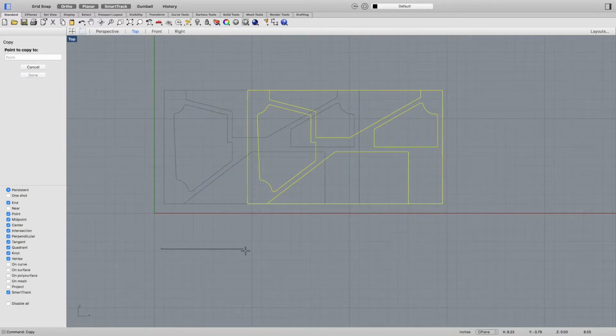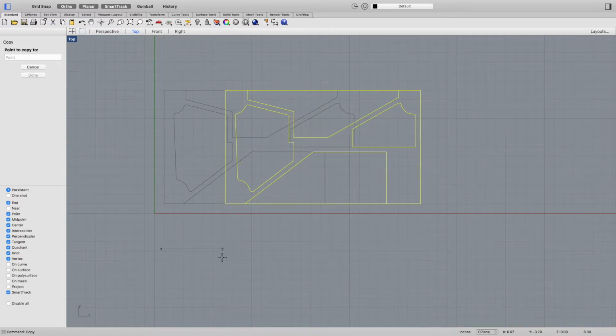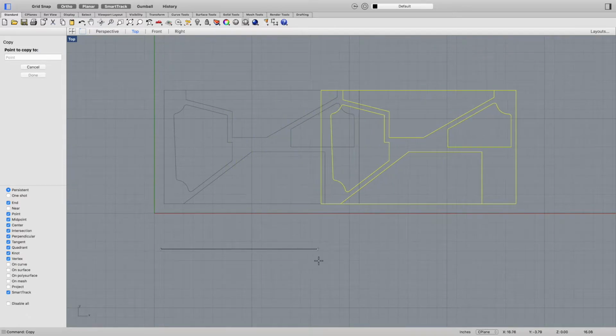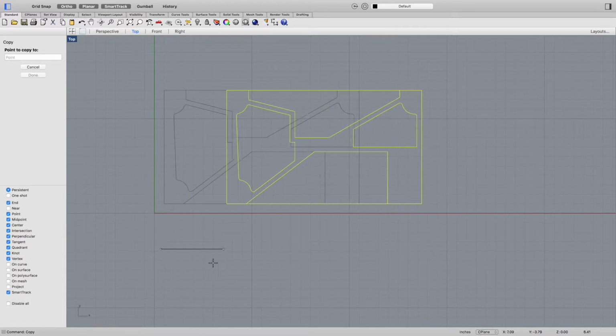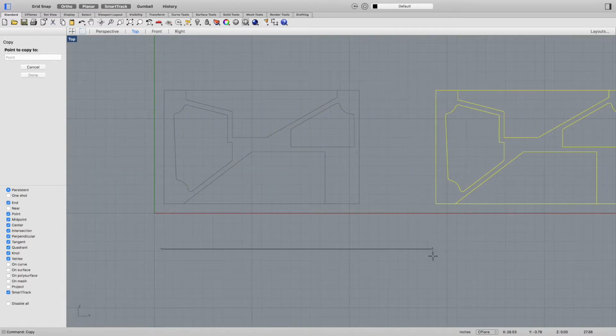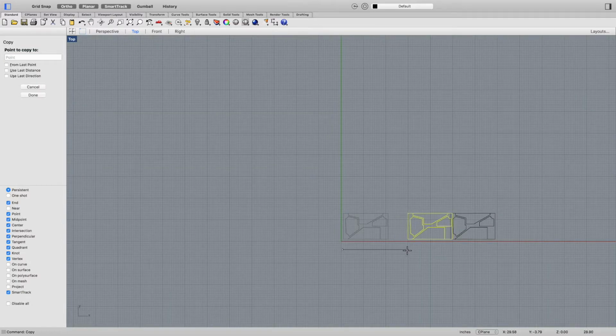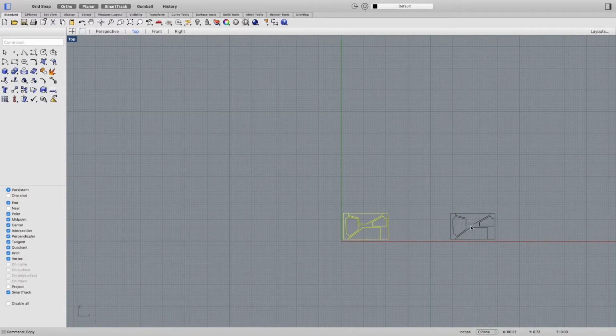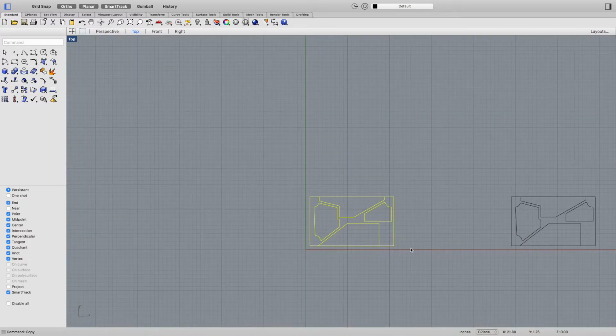And whenever I'm moving things, I don't click on the actual object because I've got all of my object snaps on, and sometimes it makes things move squirrely. So I'll click a base point below it to move it. So I'm going to go 48, enter, click. And the reason why I do it by a number, I keep it at 48 inches, is I can move it right back 48 inches if I'm missing any geometry. So I'm always aware of my measurements.